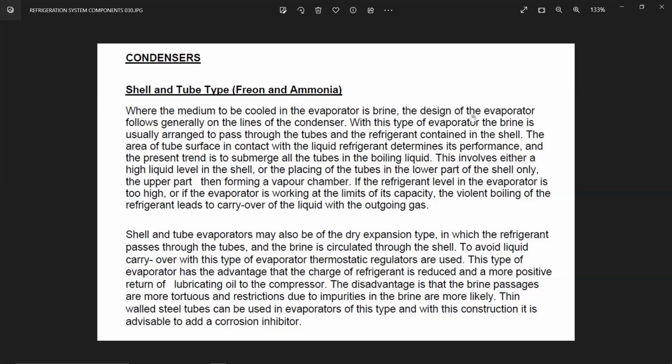Then the other thing is that you can have these chemical brines. You can have some specialty chemicals added to the water to give it anti-corrosive properties as well as enhance it, so the refrigeration effects will also be better. But generally, as I said, ethylene glycol is also used. You would have seen ethylene glycol in smaller systems, like for large refrigerating holds over there. Where have you seen this ethylene glycol, on a ship or somewhere?